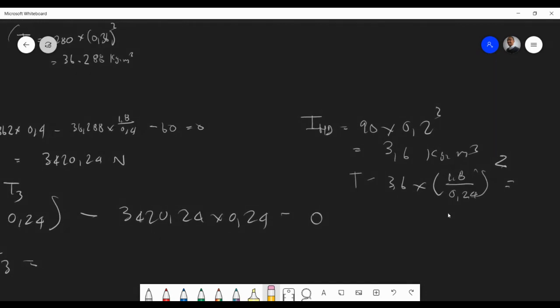So I'm just checking my torque here. I'm not really happy with the values I'm getting. My angular acceleration is, why am I squaring this? That's the thing. It's not. This is wrong. So it's torque, your inertia times alpha. Your angular acceleration is 1.8 divided by 0.24. You get 27. So T is 27.